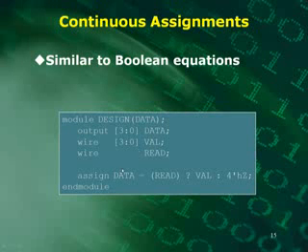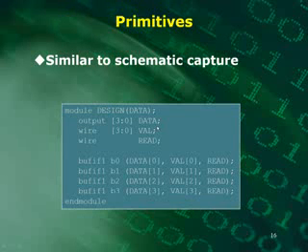Okay, here's another method you can use for doing combinational logic. You can use the assign statement. So you just say assign data equals, and then based on read, either value or the tri-state. So for simple things like that, that's much better. You can also do things where you instantiate the primitives. And here we've instantiated these buff-if-ones, 4 of them. That's the instance name for them. And that does the same equivalent thing, and that too is acceptable. So that's kind of like doing schematic capture where you're plunking down the parts and connecting them up.